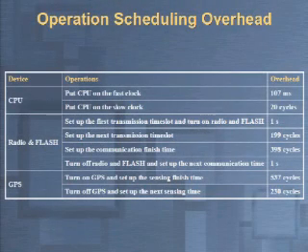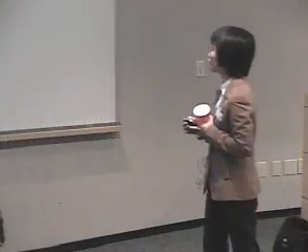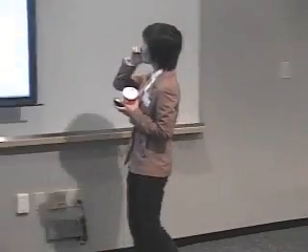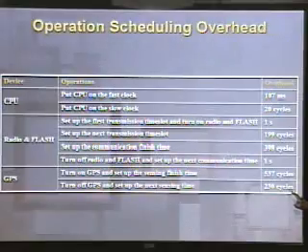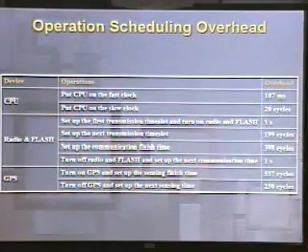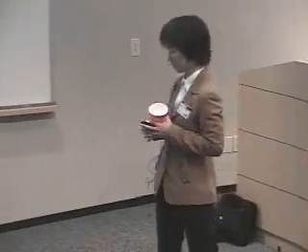This table gives you some typical overhead in operation scheduling. The overheads are mostly at hundreds of cycles, except some large numbers caused by specific hardware attributes. For example, to turn on the radio transceiver, you need to wait for 1 second for the voltage to be stable and for the radio to be fully woken up.